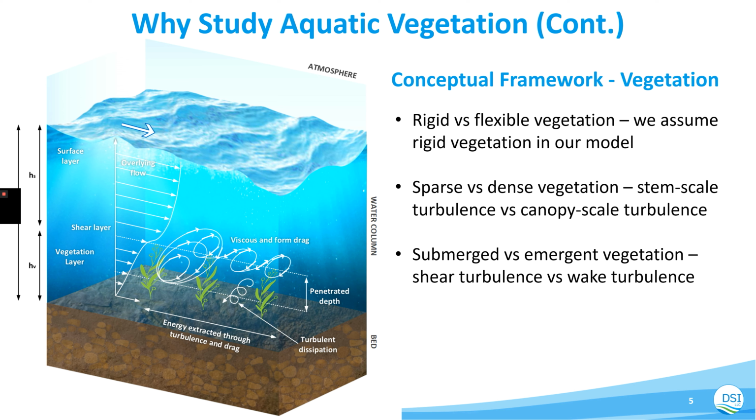So some is submerged. For previous research, we just took the vegetation as roughness, because submerged vegetation has roughness characteristics. But in current research, we focus very much on emergent vegetation because, for example, if you take vegetation at a large scale, like the tsunami: in 2011, the Tohoku tsunami happened, but they had planted a forest along the nearshore. So it's the first natural ridge to attenuate the tsunami in the nearshore. So this is why emergent vegetation is very important for recent research.